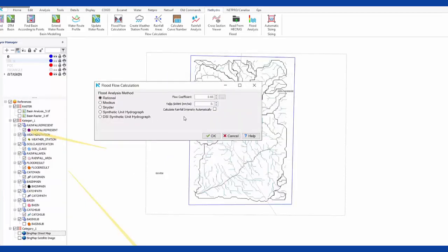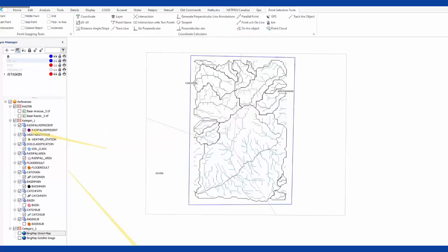Okay, 0.85. And as a rainfall intensity, I will use, actually I got the reports, but it's fine. I will use something like 30 because in the other stations were 20s and only one station was 36. So I will use 30 for the rainfall intensity.